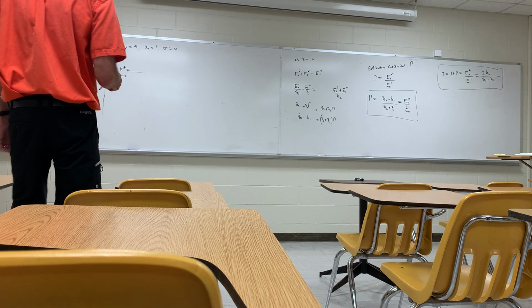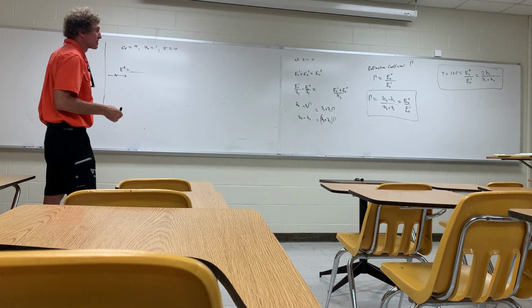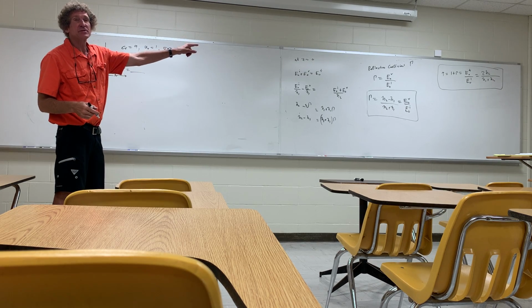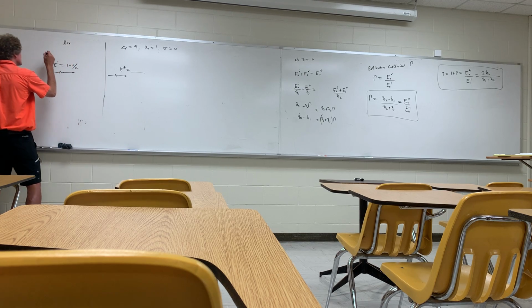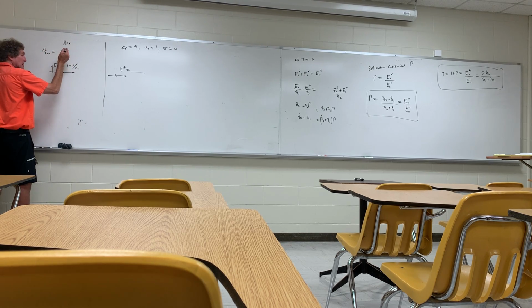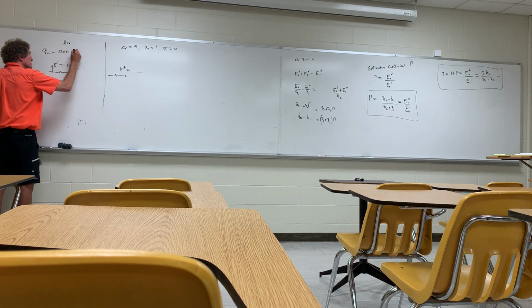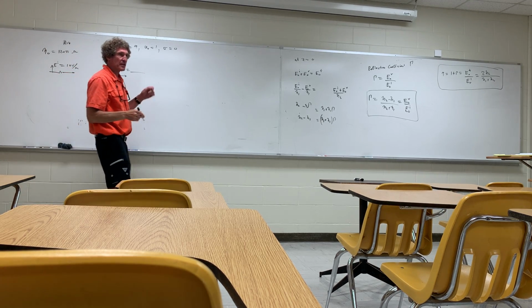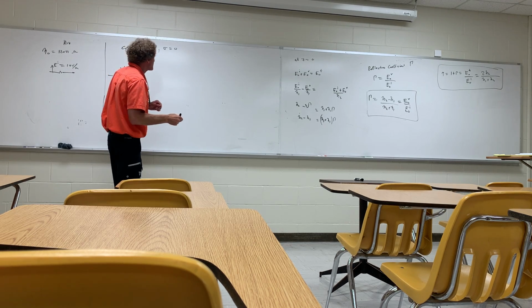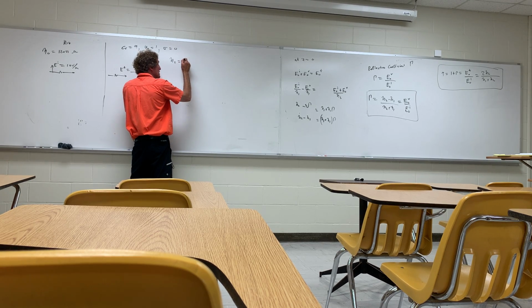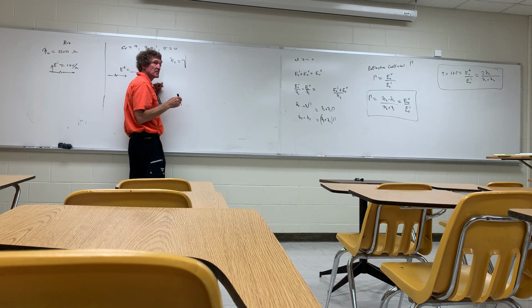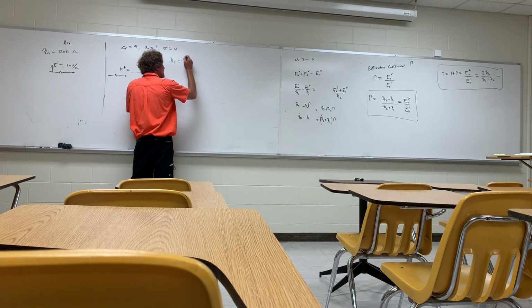Well, obviously the one thing we need is what? The intrinsic impedances. Do you agree with that, class? Gotta have that. So what's the intrinsic impedance of free space or air? 120 pi ohms, right? What is it over here? How do I get it? I would say the intrinsic impedance of region 2 would be equal to the square root of what? Normally it's j omega mu over sigma plus j omega epsilon, but since sigma is 0, it's the square root of mu over epsilon, right? Y'all agree with that?